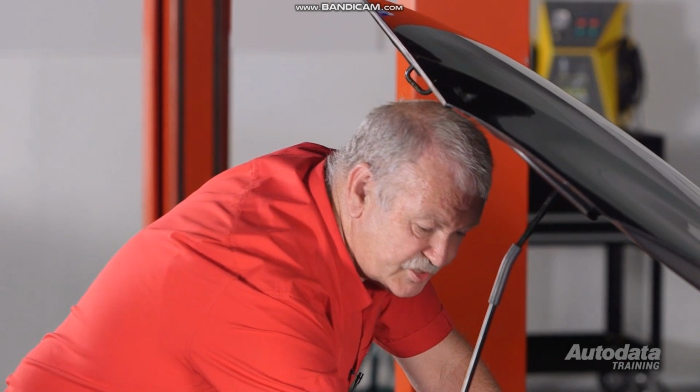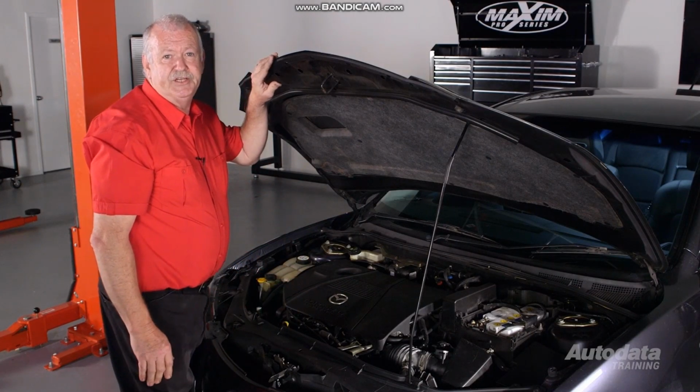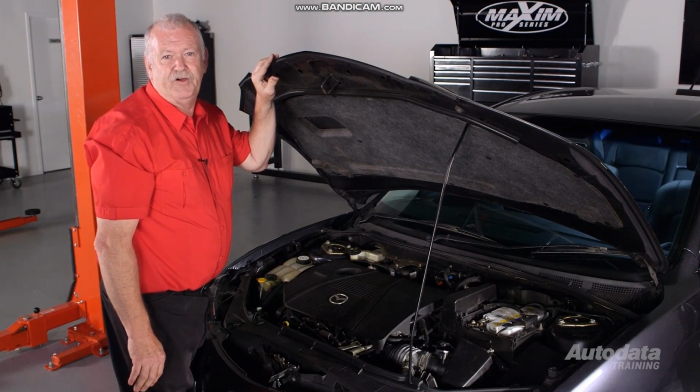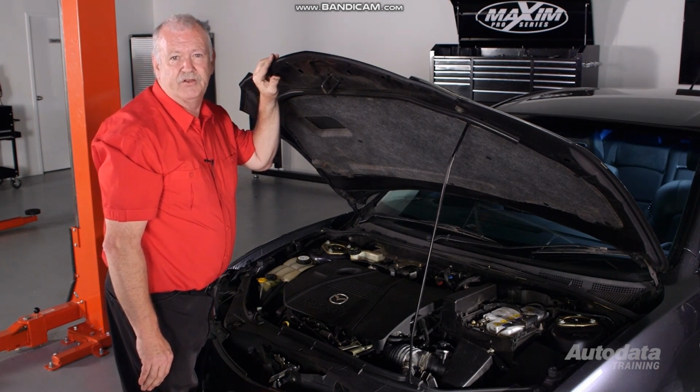There you have the diagnosis of P0101 and P0104. Make sure you check all areas of concern. Don't assume that things are correct. Test them. And as with all DTCs, once you've found the fault, clear the codes, take it on the appropriate drive cycle and retest.